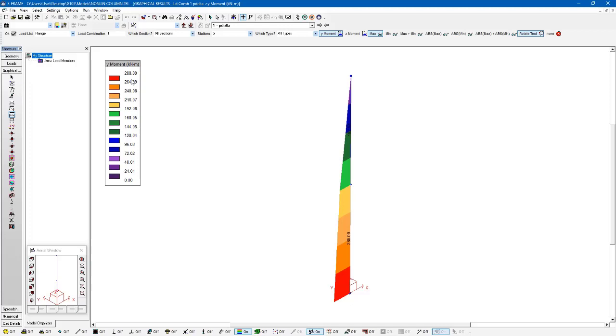We don't get the advantage when we just use one load increment of updating the geometry matrix as we go through this analysis, which can actually have a big effect because the nonlinear analysis can consider the change in geometry as we add more and more loads, whereas the P delta static analysis doesn't do that. It just looks at the stress stiffness matrix.